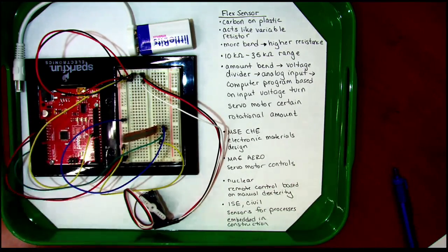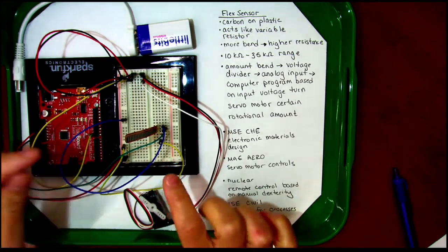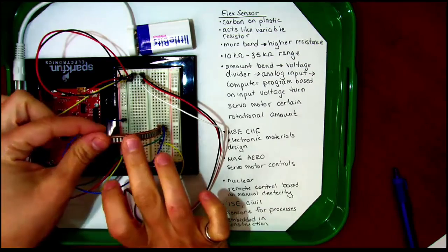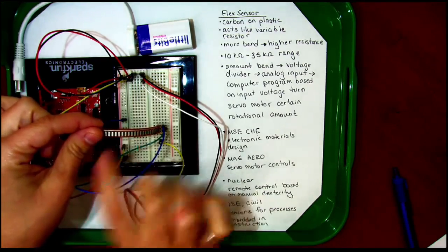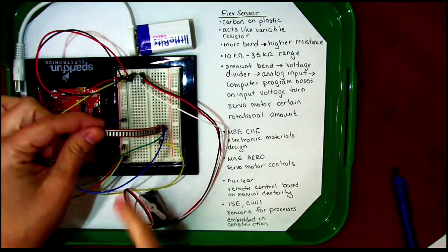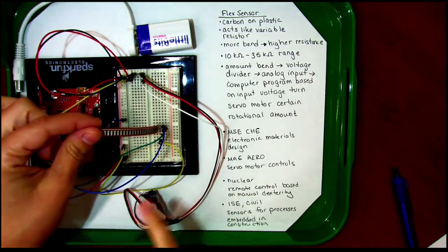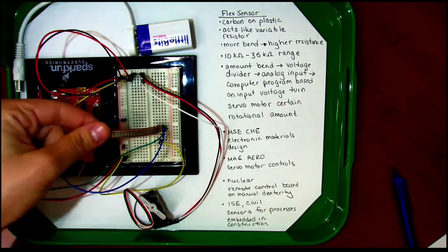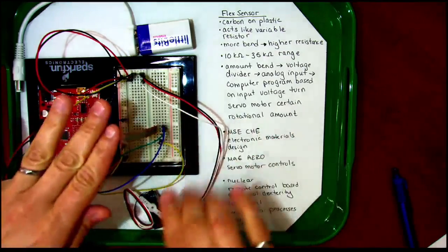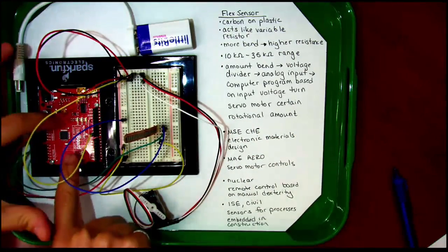We're going to show another example of a voltage divider. For all your majors, this comes into play a little more, and that something is becoming a control for a signal. In this case, it's a flex sensor, so you can embed this in any type of engineering device. We're sending voltage to it. By how much you flex it, it varies the resistance. It sends a reduced voltage into the little computer card.